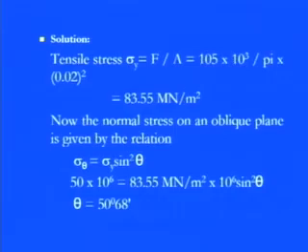So sigma theta, the normal stress at the oblique plane, is equal to the applied stress, sigma y, into sin square theta. But we don't know the angle of the plane, that is, where the oblique plane is cutting at that particular point. We would like to know that.